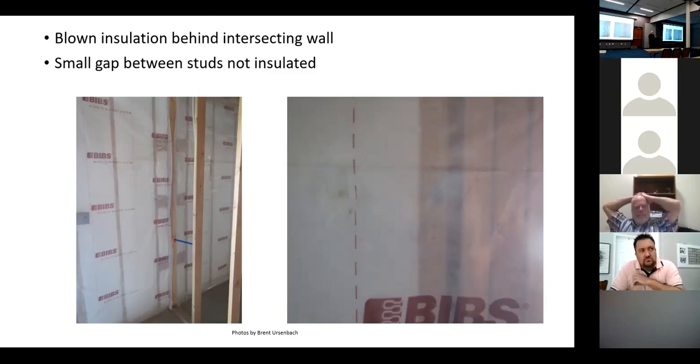In fact, with the couple of them that I allowed to be put in, when we first decided to allow them, I went out for an inspection, and the guy installing it kind of freaked out because I said, well, you didn't install it per the manufacturer's requirements. And he says, well, that's going to cost more. Well, I don't care if it costs more, but if you want it to work, they want it sealed, run down the rafter, and then a caulk seal around the perimeter, and all the seams taped and everything.